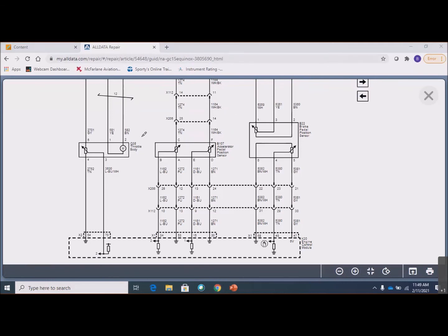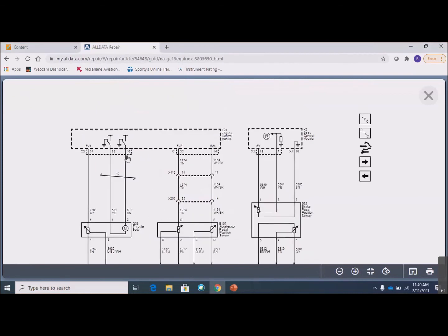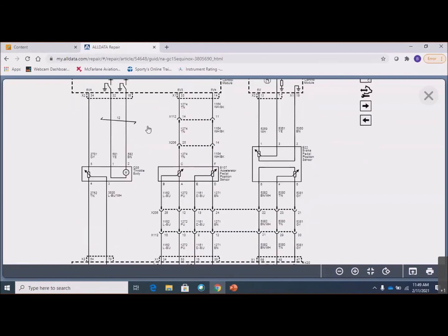If we go over to here, we have an electronic throttle body. And the electronic throttle body has two pieces to it. So the first piece is the actual electric motor that opens and closes the throttle plate. So, this is a pretty simple setup. It's a little electric motor. The computer can energize either one of these wires. The other one's a ground, so it can run this motor clockwise. It can run it counterclockwise, and so the throttle plate will open and close. It does have a default spring-loaded position, but we'll talk about that on the output side.